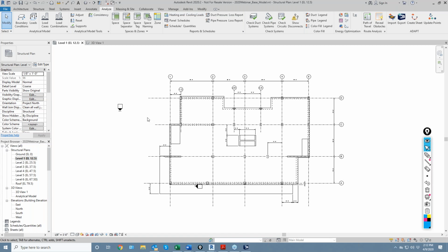So the first question, when you put a rebar mesh in the model and calculate the rebar needed with calculate rebar plan, are those bars additional to the mesh? The answer to that is yes. If there's a need for additional reinforcement and the base reinforcement is not enough, then the program would add additional rebar to meet either minimum or strength requirements if the base rebar doesn't cover that.